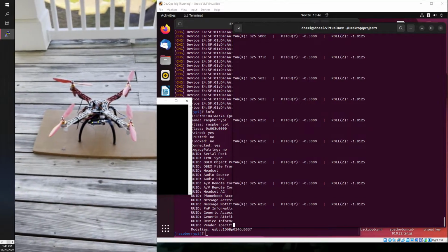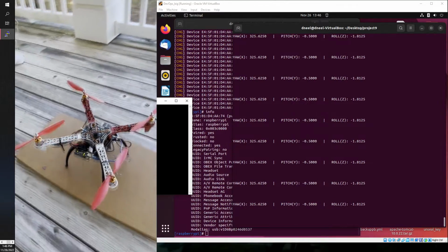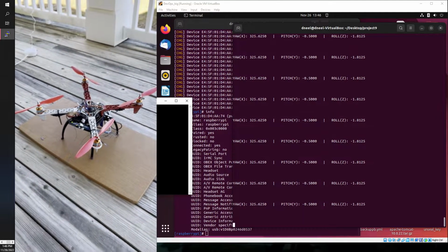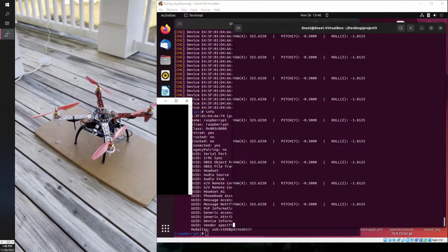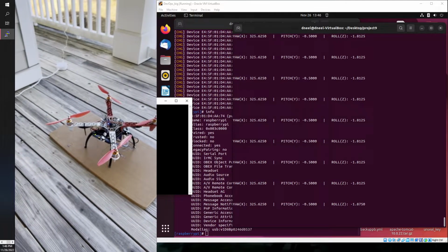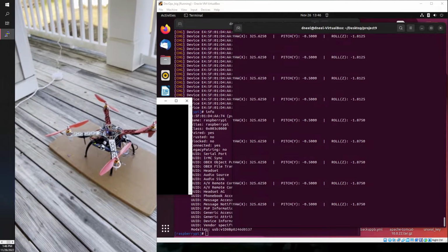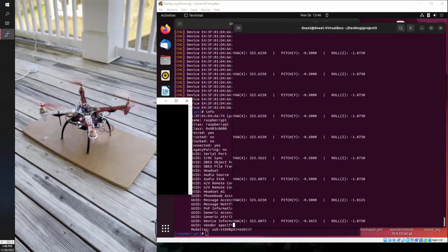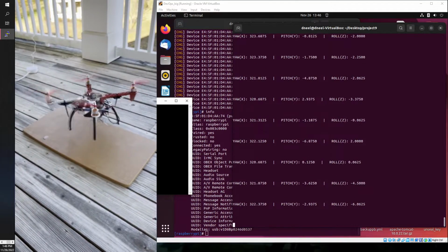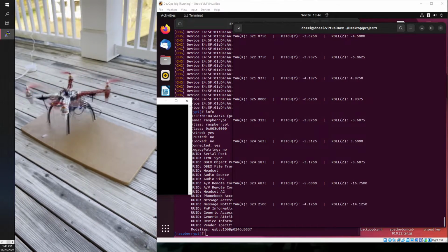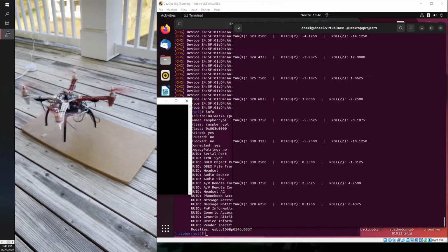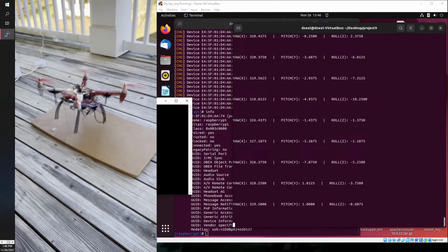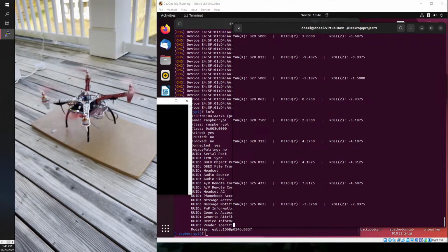Now he's walking over to start actually flying this bad boy. Flying in quotation marks. And we see the roll, pitch, and yaw are static while the thing's not moving. That's always a good sign. But as soon as it starts wiggling around, we get a lot of slight variations. It's not doing any significant loop-de-loops here, but we can see that the orientation sensor is getting data and sending it, and we're receiving it over Bluetooth onto our host machine.